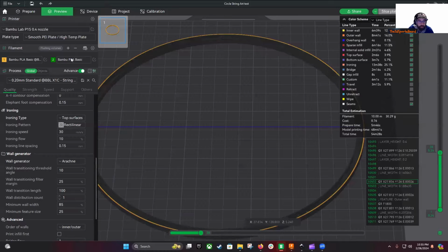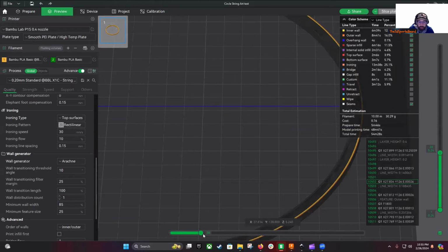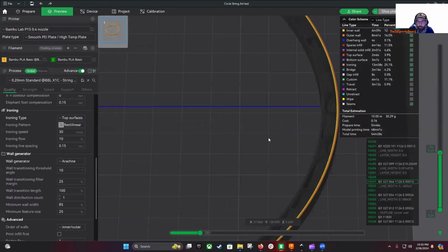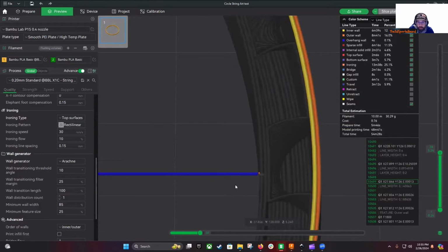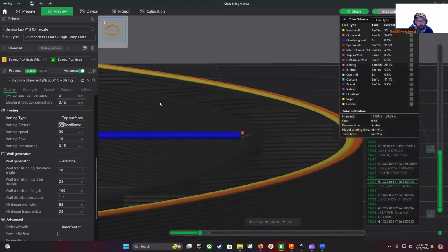And we'll go over to Bamboo. And I've already got one here. This is exactly what we just did. So let's show you how this fails. If we go up this layer where the string would print, it might print, but here's the problem. Look at that connection point. Chances are that's going to fall, specifically if we're doing like 60 or 80 of these. It's not going to connect.